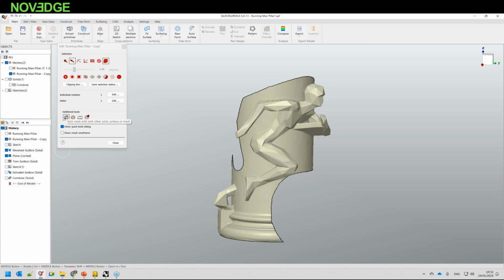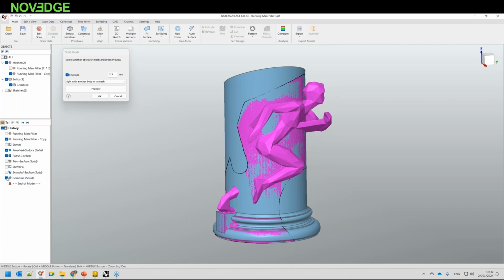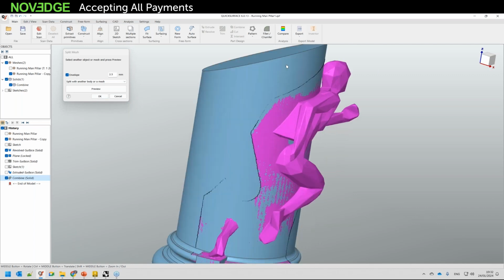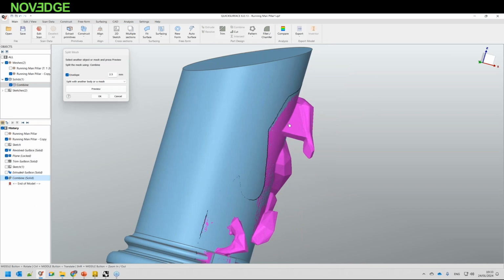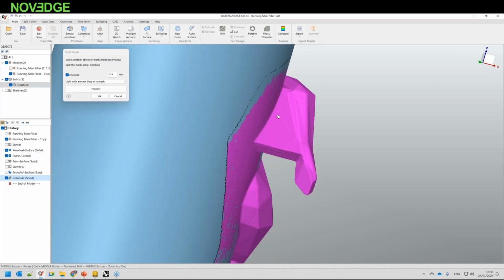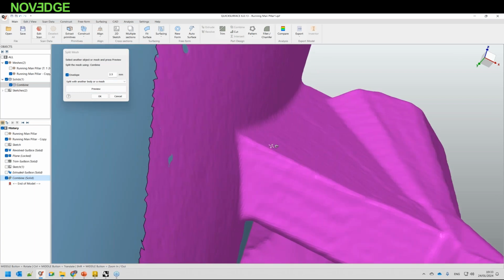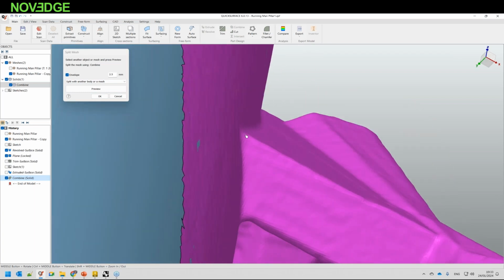is we'll use our tool, which is called split mesh with another cut model. And I'm going to show you what I mean with this. If you remember, we created the big solid, and what we have here is a function called envelope. I just pre-select my active shape, which is in blue. How the envelope works is that it creates an envelope around it and deletes everything from the mesh. And it has a parameter, 2.5 millimeters. The reason for this is that this transition may have a fillet here, and I want to get rid of everything. Let me just press a button so you can see what I mean with this.